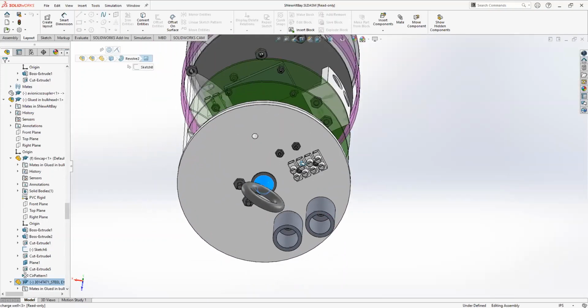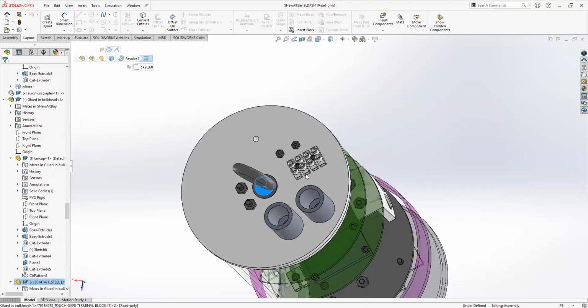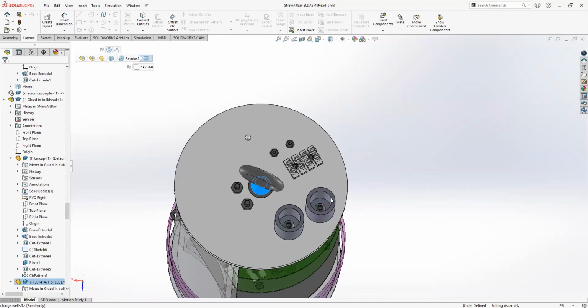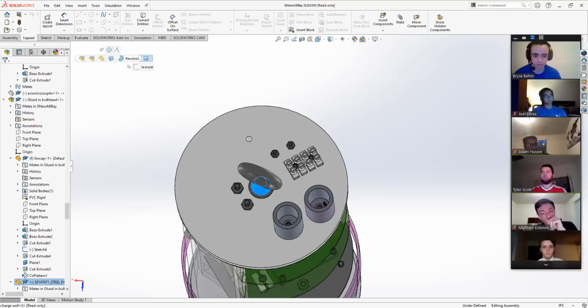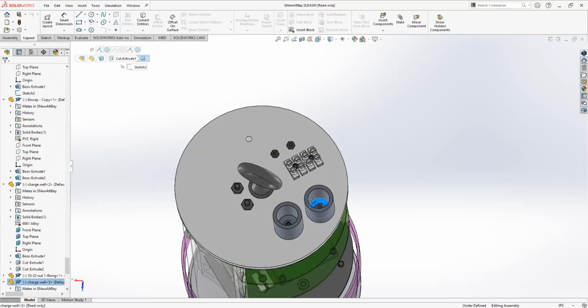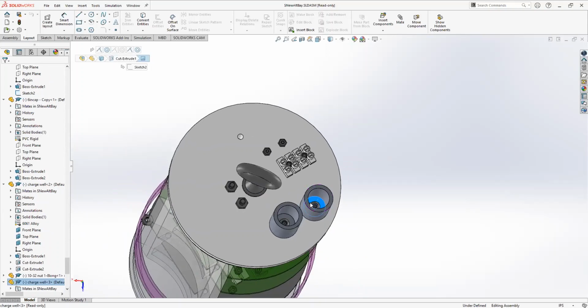And then your little explosions that are coming from the altimeters will go into these little guys. These are made of aluminum, and we can make them super easy. Basically, you put in a bunch of black powder, you put wadding to make sure that it's not going to be shifting around during flight. And then your altimeter sends an electric current through a little piece. And that piece, as soon as it gets current, it blows up. And then that blows up the rest of the little black powder that you put in here. And that releases enough pressure to separate pieces of the rocket. So if you're ever confused about how the rockets are actually separating, that's how she's done.